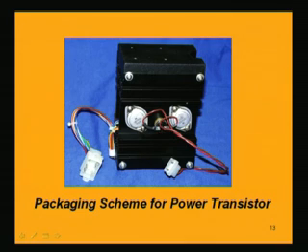And we can now visualize this as a flow taking place from the junction of the transistor finally into the surrounding air via this medium of case and then heat sink. So, what is happening is basically we are visualizing the flow of the heat, which is analogous to electrical voltage and current.